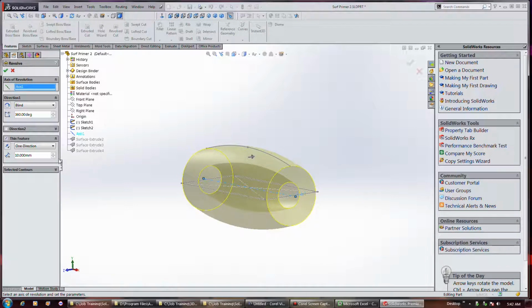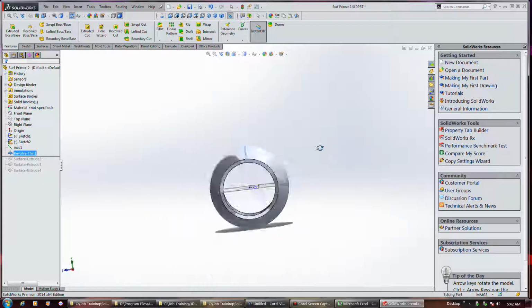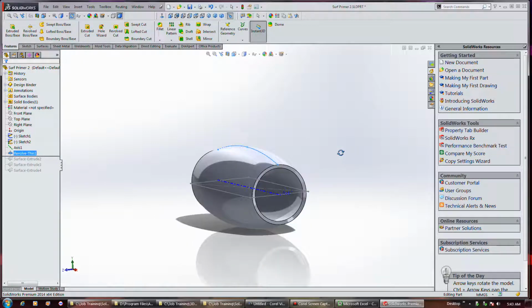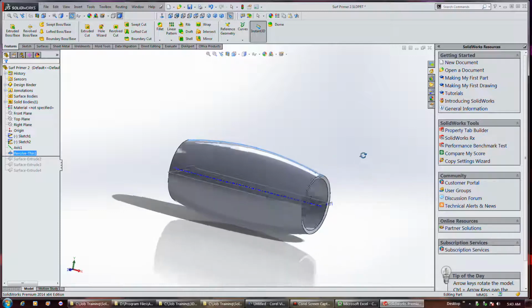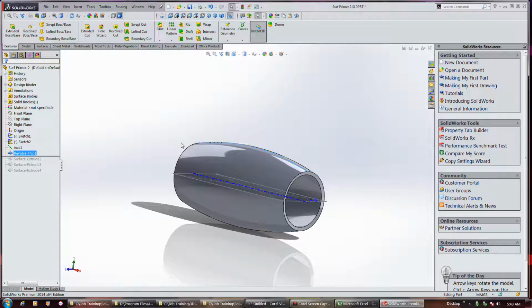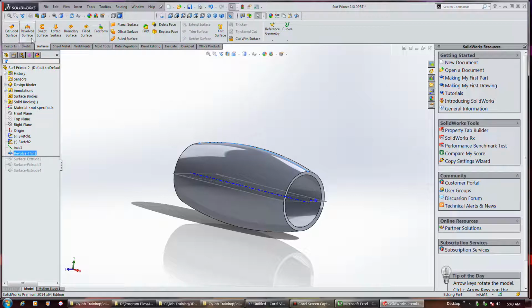But at any rate, it is creating an automatic surface, even though, as a thin wall, I mean, it's creating a solid object as a thin wall, even though we didn't actually have an enclosed sketch. But that's opposed to if you accidentally select that versus the surface, if you intended on making a surface instead, that shows you the difference between the two commands operating on the same sketch.